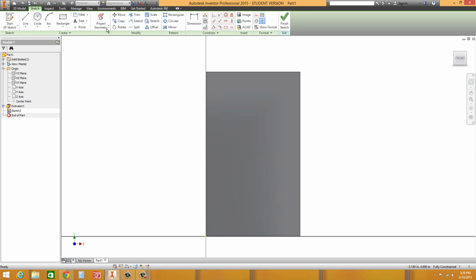Okay, moving along here. Now I'm going to go to the rectangle tool again. And down at the bottom corner you'll see it easily snaps to this edge. I'm going to go ahead and click on that. Now over here you can see sometimes it snaps, and in other releases, I don't know why, but sometimes I'm not able to get it to snap onto that edge. And I just want to share with you something in the event that you're unable to get it to snap to that edge. I'm going to hit escape first.